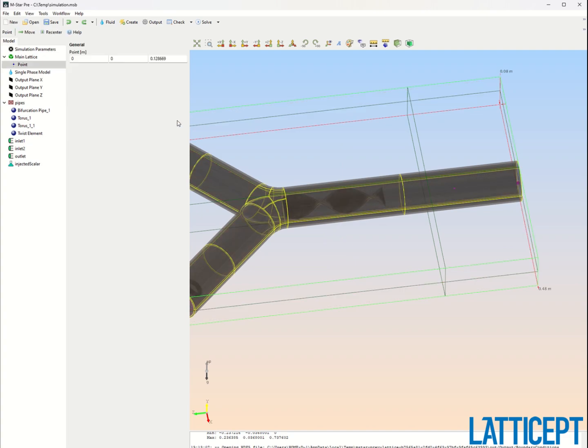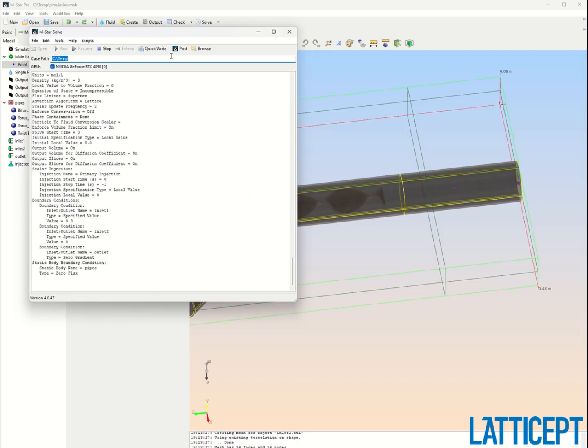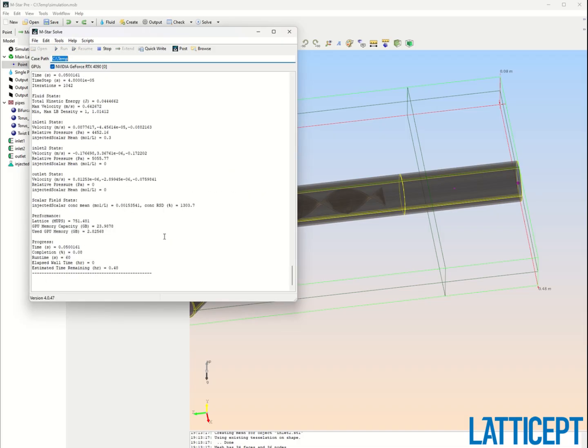So this should mix. Now close this, save that, click solve, delete whatever's there. Yes, I want to do that. Run. Yes, I'm sure. Off to the races. Mixing is occurring. Check our LB density, looks good. You can see our inlet pressure has gone up, which is what you would expect because we have literally something blocking the flow now. But we weren't talking about optimizing the pressure drop. We were talking about creating a static mixer. So then click post here. Let's view what's going on.